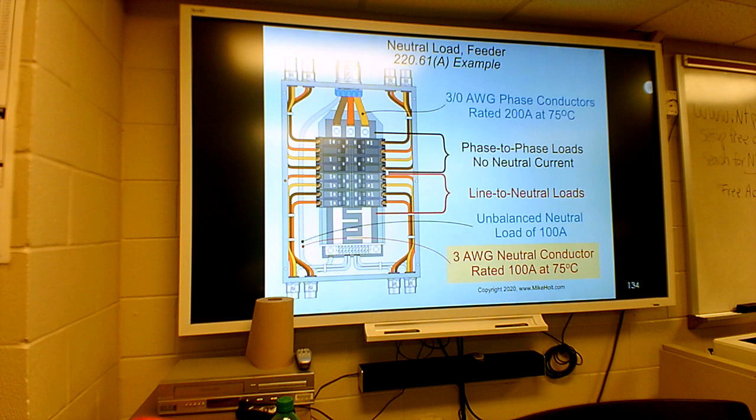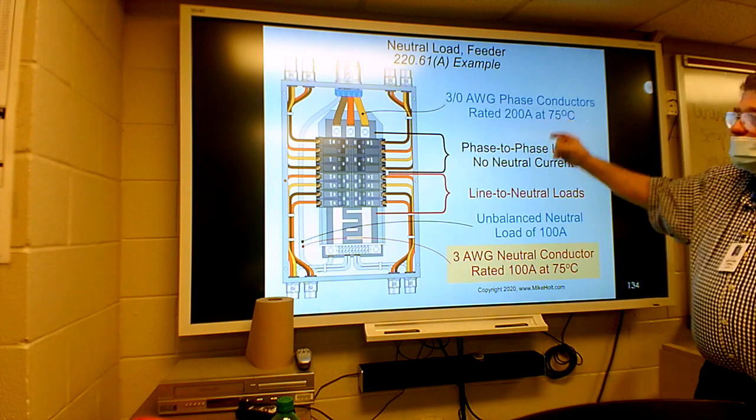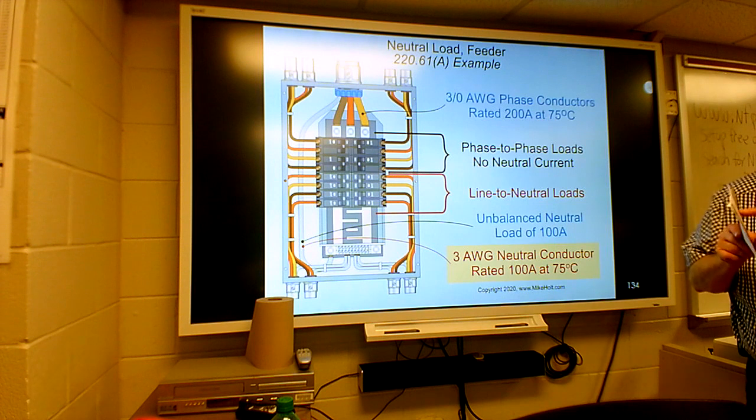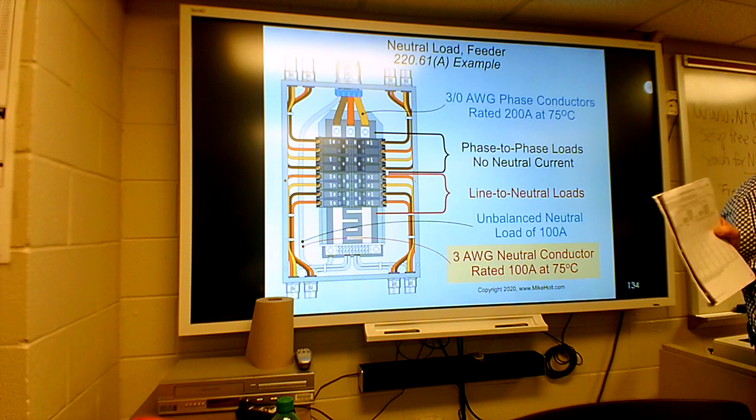When you look at it, it's telling you you've got a 200 amp panel, a 200 amp service, and the terminals are rated at 75 degrees Celsius. So what column do we go under in the wire chart to pick the wire?